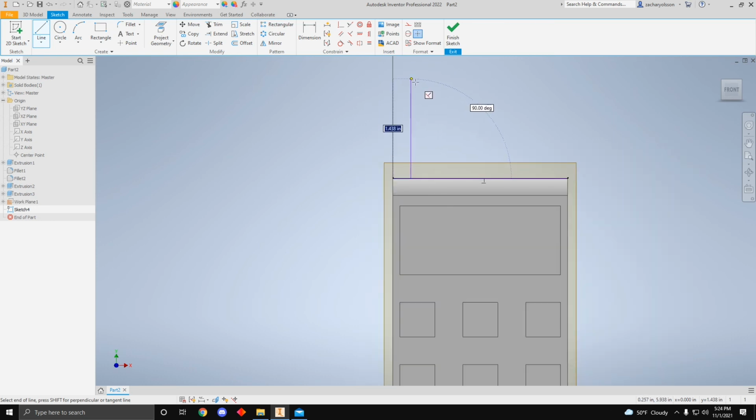We'll make it 1.5 inches maybe, so we'll go dimension, just the line, and go 1.5. Then we don't want it to be a straight up post, right? It's going to be a little tapered, getting smaller towards the top, just because that's, I suppose, style. I'm not quite sure why they do it, but they're not straight.